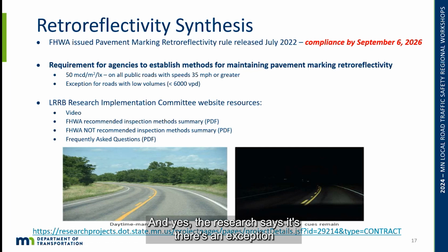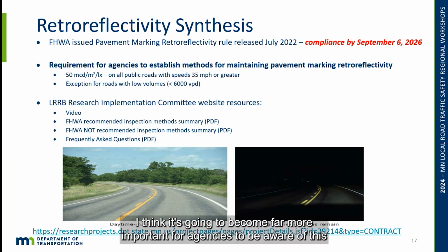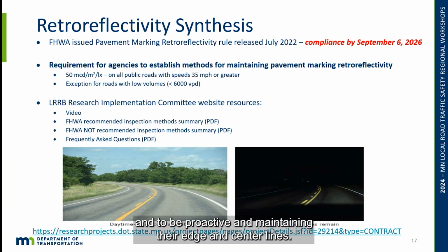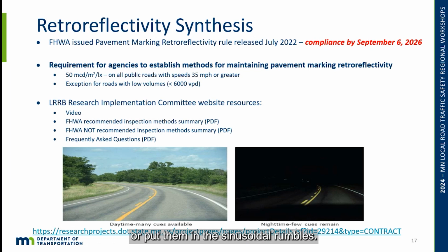And yes, the research says there's an exception for lower volume roads, but with this requirement out there, I think it's going to become far more important for agencies to be aware of this and to be proactive on maintaining their edge and center lines. And again, one way of doing this is to embed them or put them in the sinusoidal rumbles, because then the snowplows can't get down and scrape the beads away. And the research says that the pavement markings will last probably 2 to 3 times as long as without taking that kind of precaution.